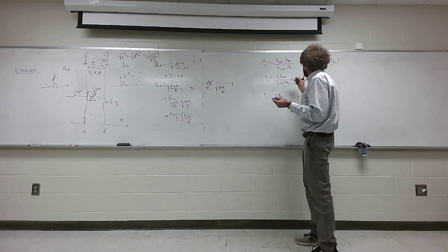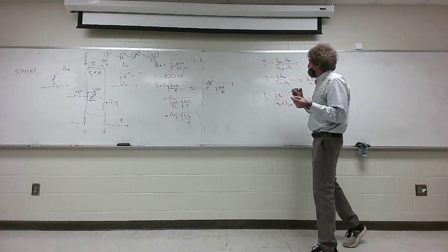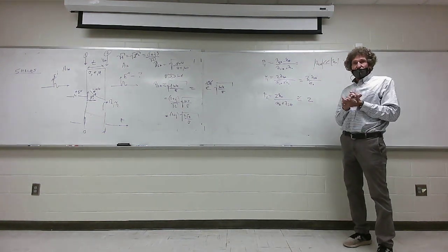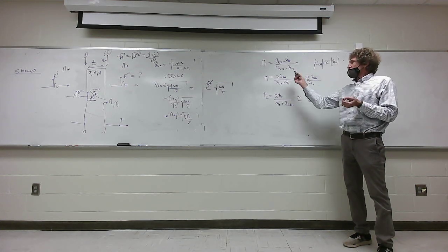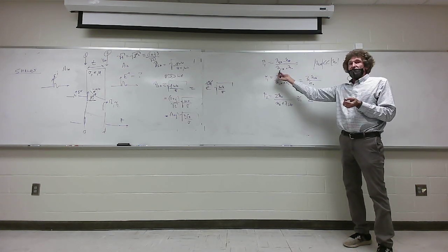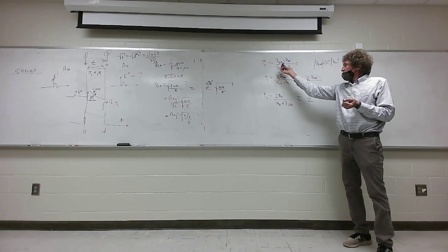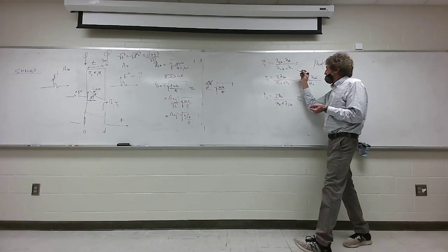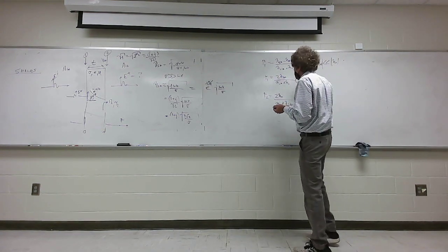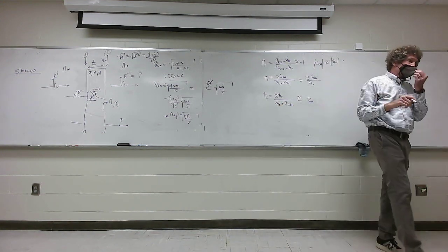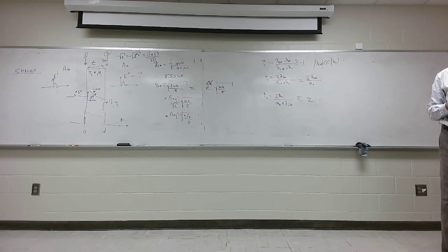All right. And then finally, this one, what happens? Just look at it for a second. Now, this isn't quite true up top, but what is the reflection coefficient about? If you look at this, since eta shield really is not a factor, put a 0 in. Minus eta naught over plus eta naught, it's about -1. So the magnitude of the reflected wave is about the same as the incident. Not quite, but y'all follow me?